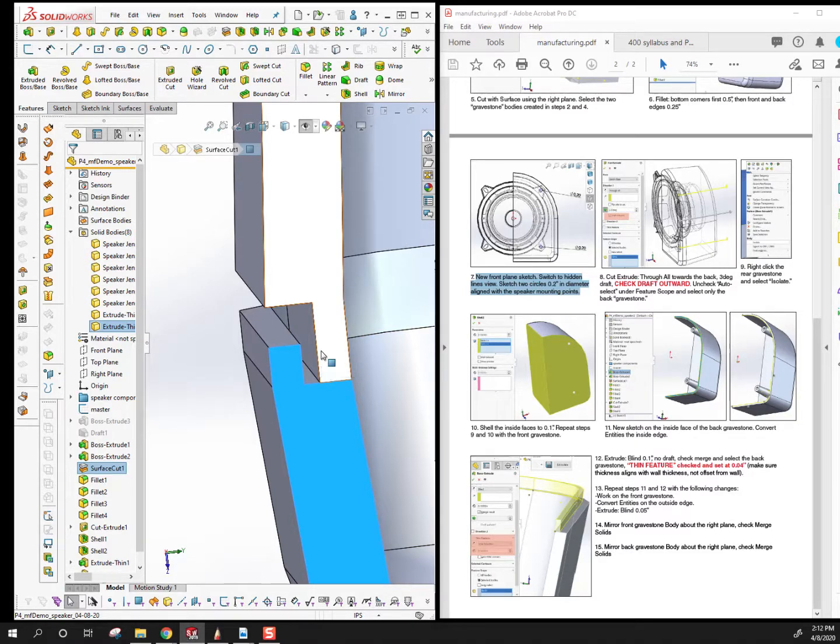I'll be perfectly honest with you all. As far as design students and your design career goes, this level of nuance probably won't matter. I would imagine you will encounter this at some point in your career if you go down the product design path. You may be requested to build a part designed for manufacturing, in which case draft is really the most important thing, and determining where the part line is. But there may be a case where you need to have a detailed part line and build in some of these features, depending on where you work and who your client is.